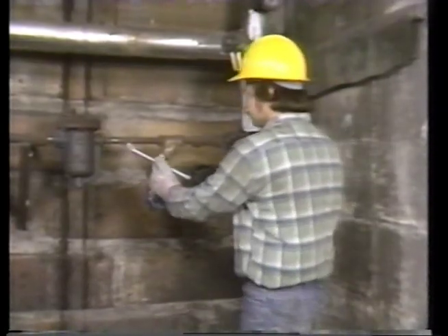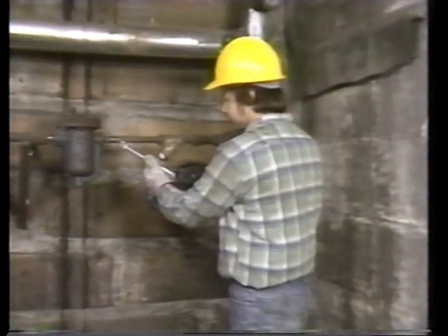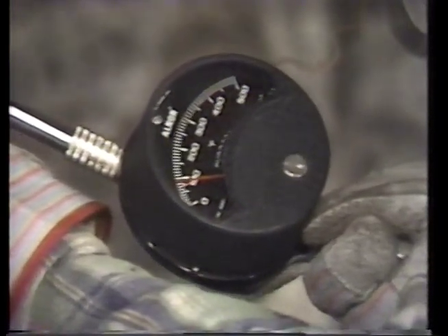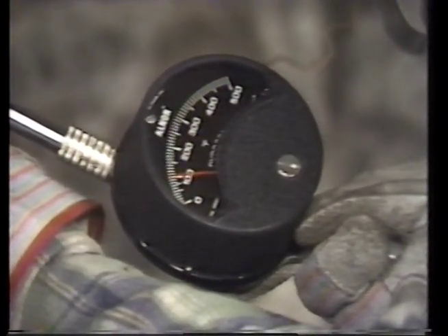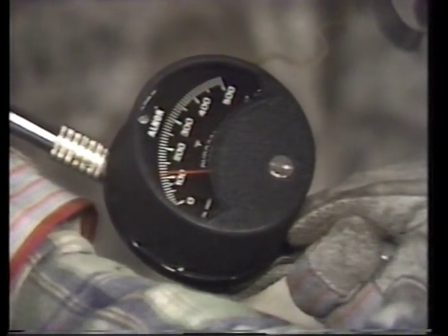What often happens in situations like this is that you're working on a system that you're familiar with. Since you know what the pressure should be, you just assume it's right and you don't bother to measure it. Now, if you really know the system, it's okay to do this, as long as you realize that if you get a low inlet temperature reading, you're going to have to go back and get a true pressure reading. Okay, let's assume you have a true pressure reading and you're measuring inlet temperature. You get a reading that you think is low.